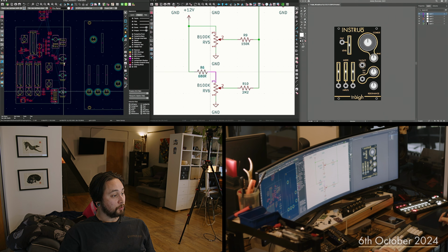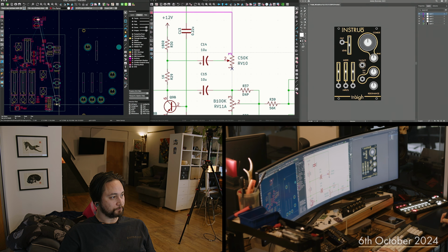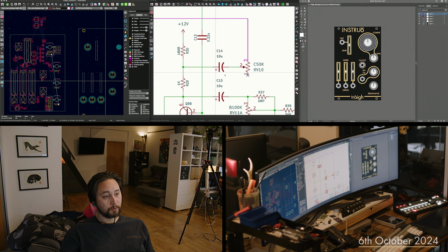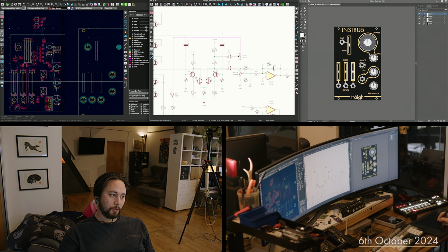Okay, so this is a long trace for the feedback pot, that's got that net and that net. So the question is, what's going to benefit from the short trace? That's a limitation. That trim pot can't be further away from there. That's tied there physically.